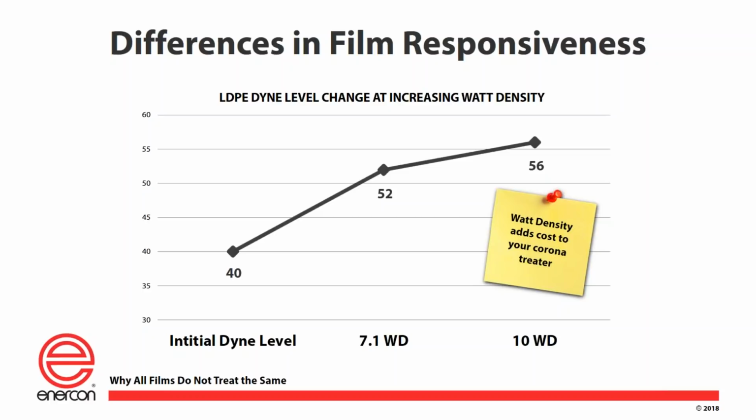Well, even if it's possible, look at what impact this has on the watt density. What did we say earlier? Typical watt densities for corona treaters are 2 to 3 watts per square foot per minute. Well, in this one example, you could be somewhere between 7 and 10 watts. So let's run this example out to its end use. You can see the example here.